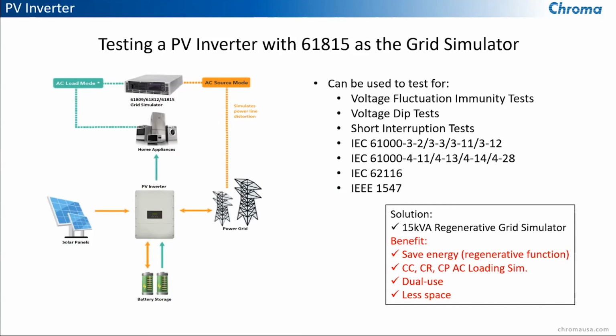Among the tests required are voltage fluctuation immunity test, voltage dip tests, and short interruption tests, along with many other common functionality tests, some of which are included in standards such as IEC 61000, IEC 62116, IEEE 1547, and the IEC 1547. Sorry, I already mentioned that one.